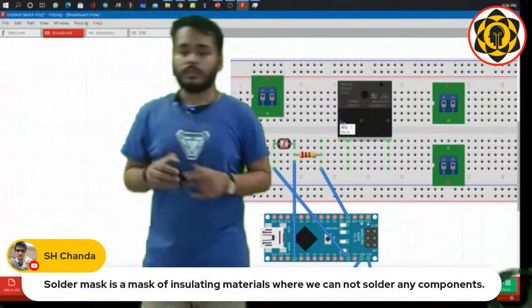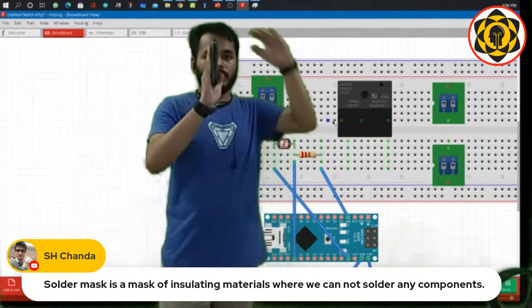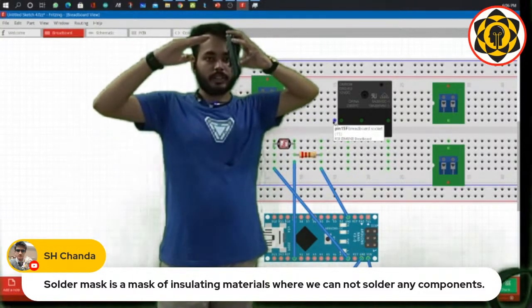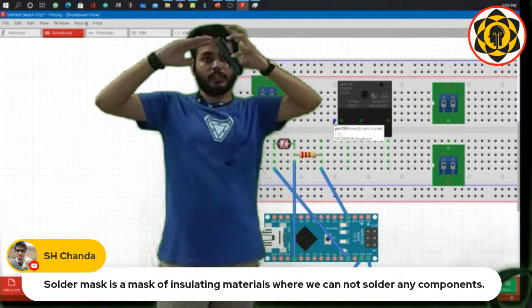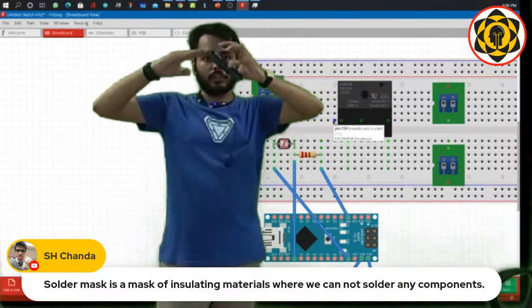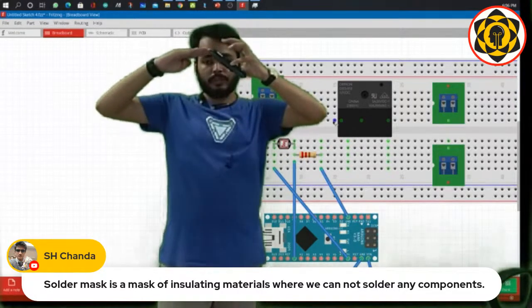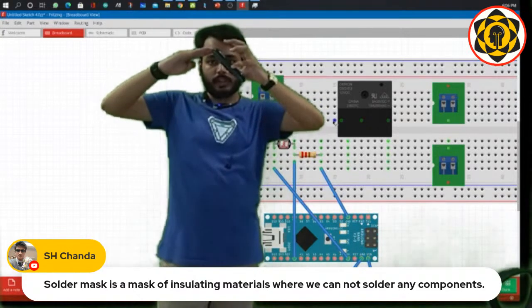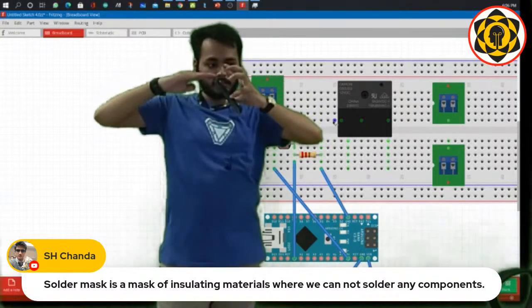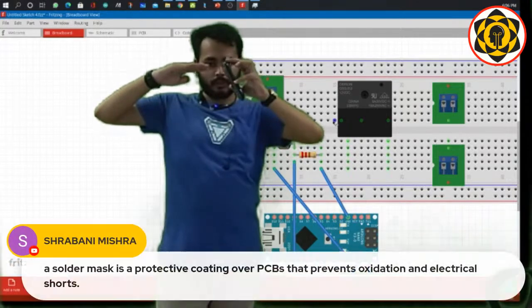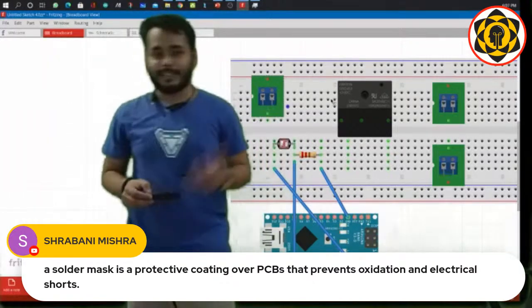This is normally open. For those of you who know relays, a relay is basically a mechanical switch. There's one port like this and another port like this. This one is normally connected when there is no power and this one is normally open. When you give power, the switch moves from this to this. So the normally closed, which was previously closed when there was no power, is now open, and the normally open, which was previously open, is now closed. If you stop the power, there is a spring action that pulls the circuit back. So it's power off, power on, and power off again. Never mind, accidents happen.